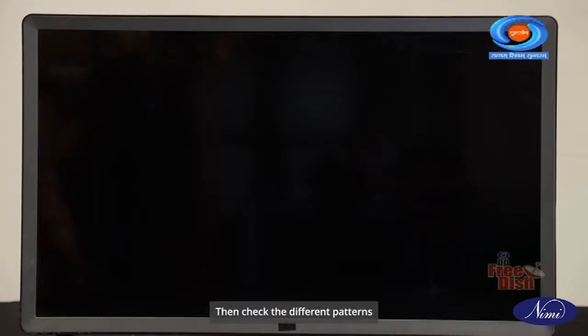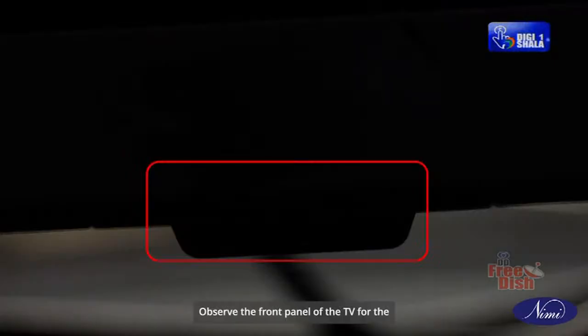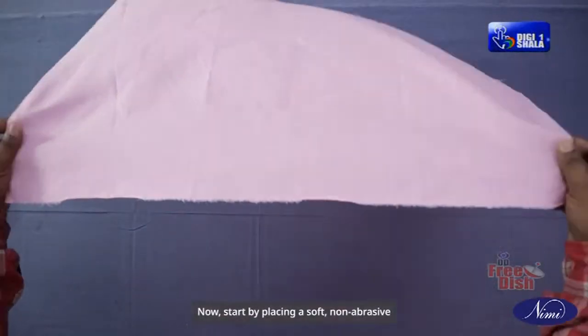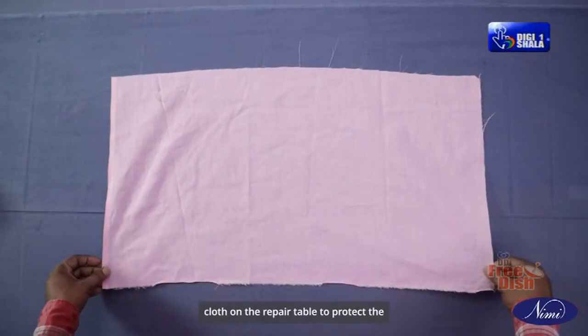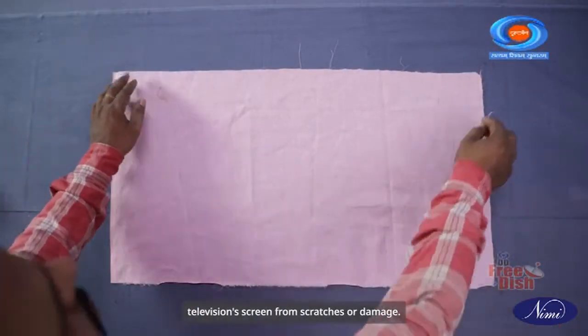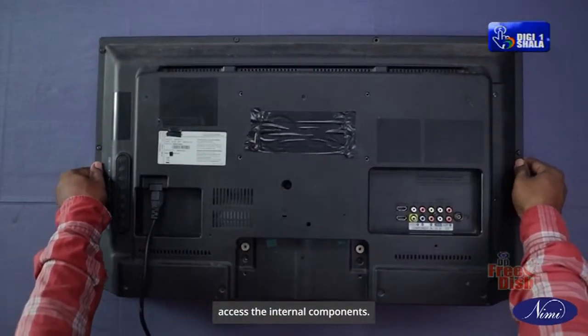Then check the different patterns using factory reset remote. Observe the front panel of the TV for the LED indicator. If it does not illuminate, this indicates that the television is not receiving power. Now start by placing a soft non-abrasive cloth on the repair table to protect the television's screen from scratches or damage. Then proceed with the steps to access the internal components.